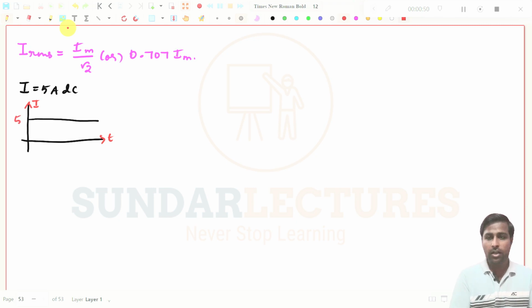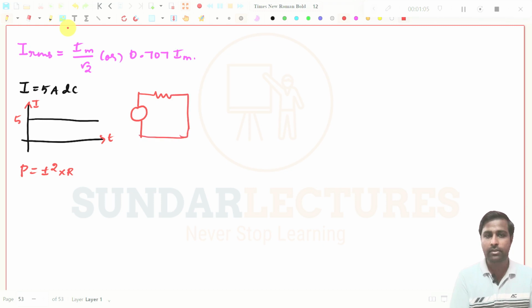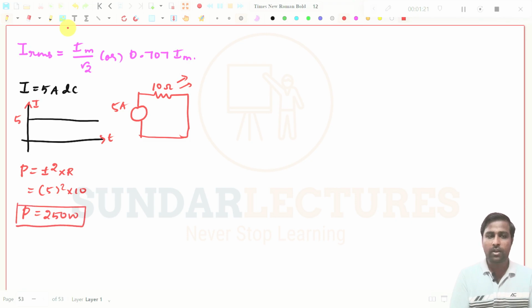If you want to find the power loss, power loss will be equal to I square into R. We have already drawn a circuit: if you are giving a 5 ampere DC source to a 10 ohm resistor, what is the power loss? We have already found this: 5 square into 10 will give you P equal to 250 watts.